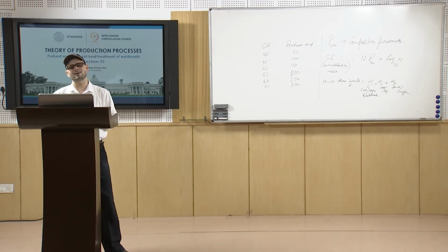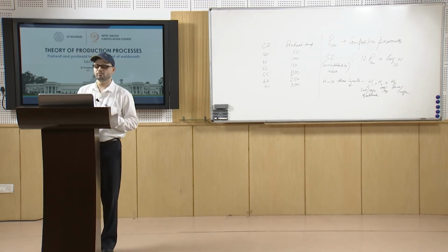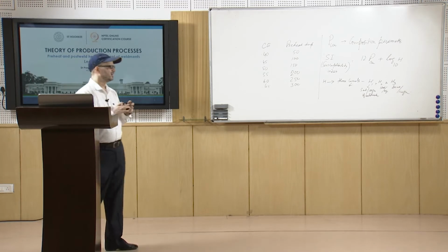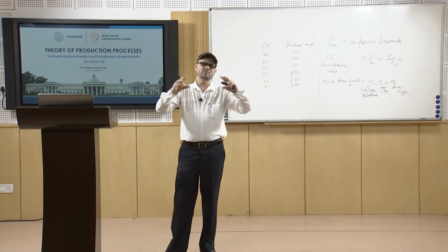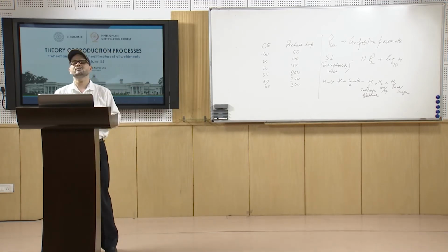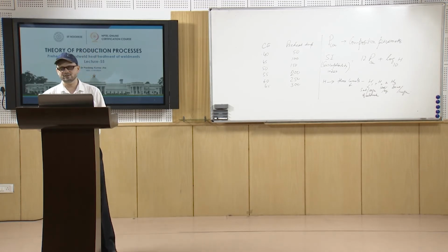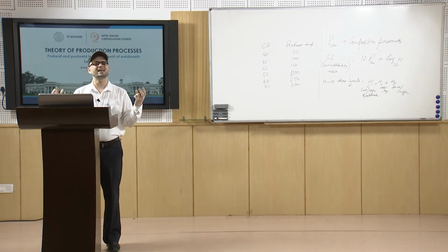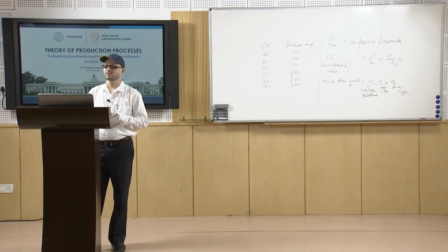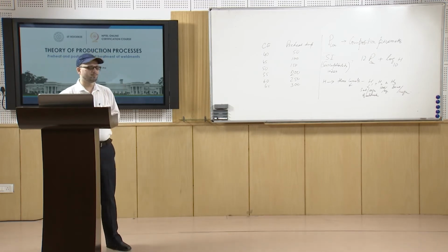Now, in that also you have different types of restraint, like low, medium and high level of restraint. So, how much freedom the structure is having, based on that you have the restraint values, and on that also the value of preheat is determined. When we talk about low restraint, it is like a common fillet or groove welded joint, where the freedom is there for the movement of the member.